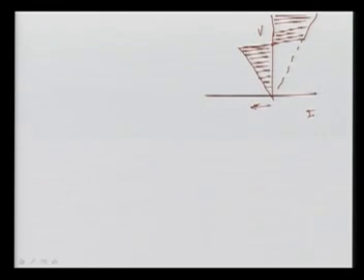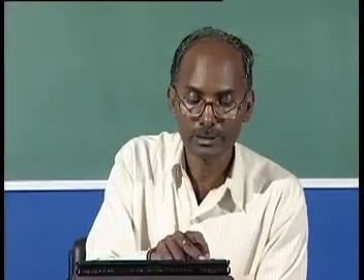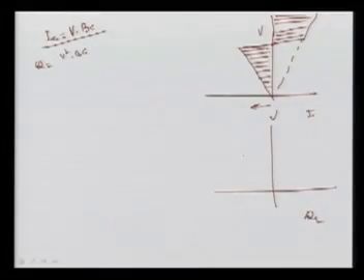Now let us go for the VQ characteristic of the SVC. I want to draw Q here and the voltage line here. Already we defined IC, it is nothing but V times BC, so it was a linear curve. Now if I go for Q, it is nothing but V squared times BC. It shows that the reactive power is a square of the voltage. The current was linear, so we were getting the linear characteristic there, and now it will be quadratic.